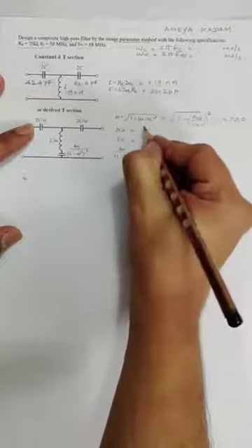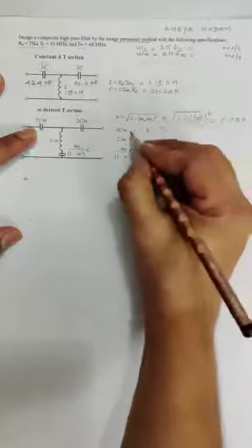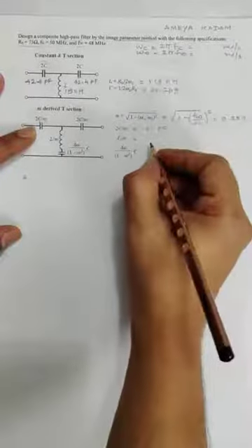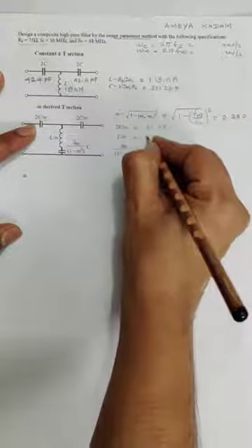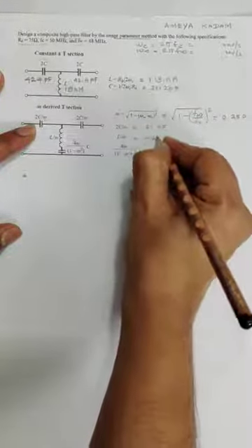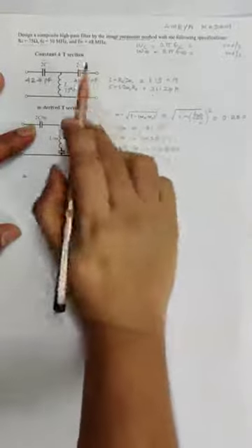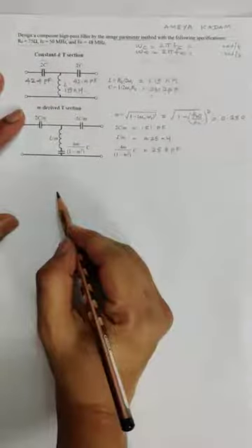So this turns out to be 151 picofarad, and L by M, 119 divided by 0.280, turns out to be 425 nanohenry, and the value of this capacitor is 25.8 picofarad. Being a high pass filter, the capacitors will be in the horizontal arm, while the inductor will be in the vertical arm. Now we have to design the matching section where M is equal to 0.6.